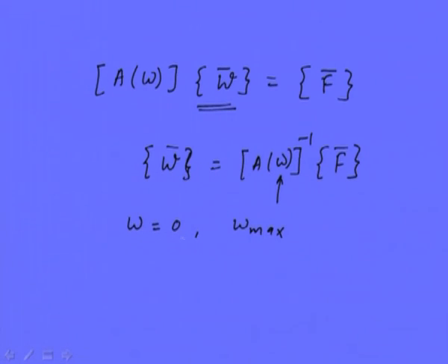If we take omega equal to, let us say, 100 rpm, we substitute it in this, and then, as we know the force, we can get the response for that omega, let us say 100 rpm. Then we can change this. Again we have to obtain the response corresponding to this separately by a different run, and so on. We can get these W bars for various values of omega, the spin speed.